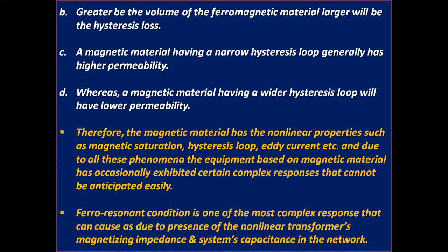Ferro-resonant condition is one of the most complex responses, which can be caused by the presence of the nonlinear transformer magnetizing impedance and system capacitance in the network.